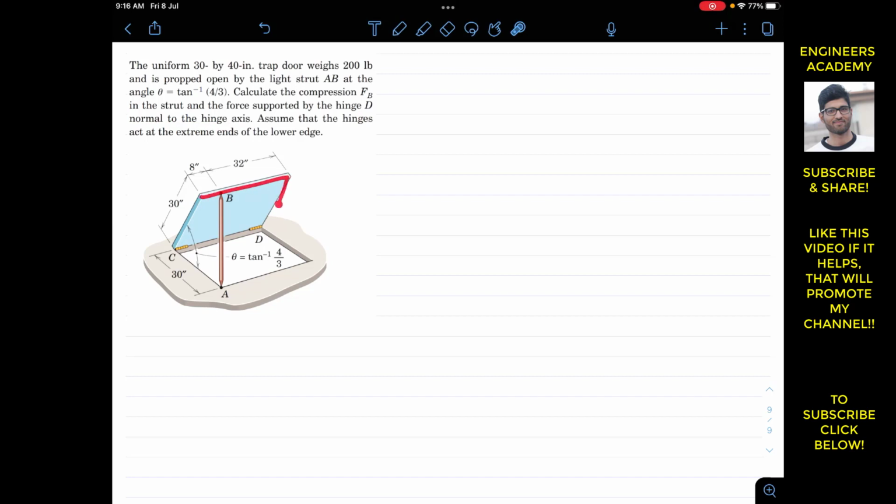So we are given this uniform trap door which has a dimension of 30 by 40 and it has a weight of 200 pounds and it is kept open by this light strut. So the strut is going to apply the force in this direction, and as a reaction the door is applying the compressive force on this strut in the opposite direction. So we have to find that compression force.